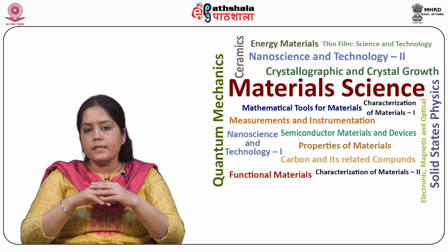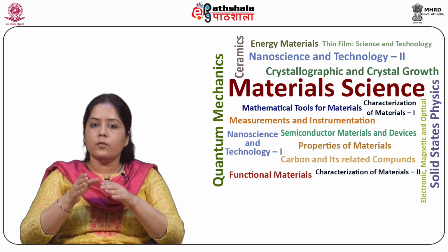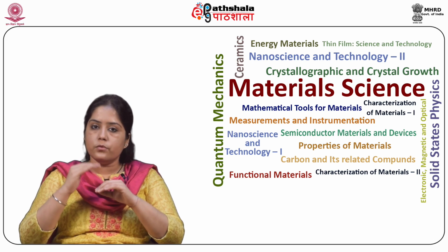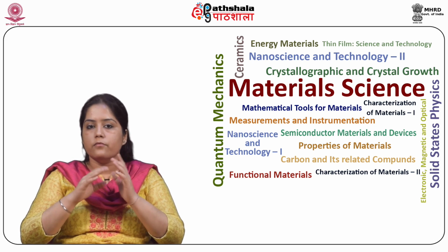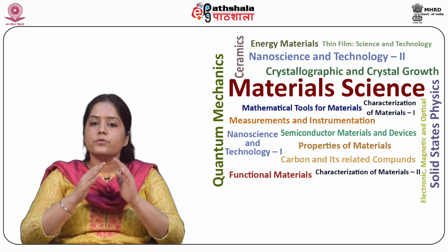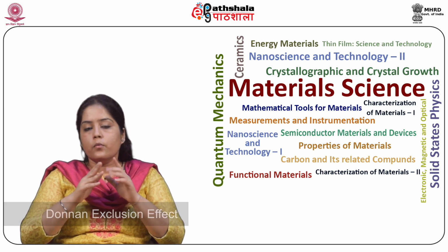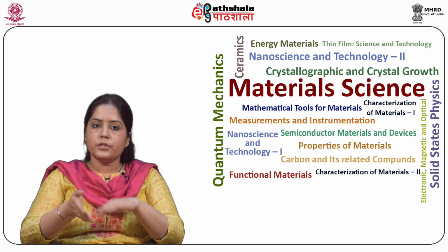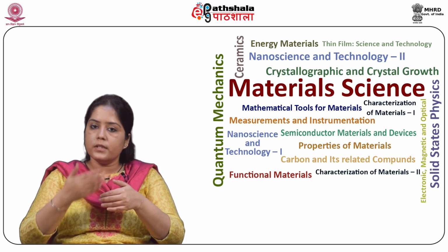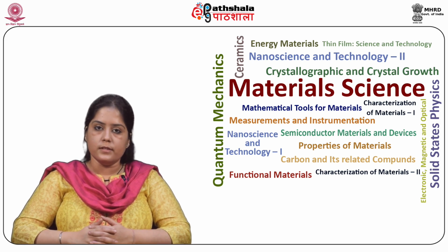However, recent studies suggested that AEM could effectively reduce the crossover of vanadium ions in VRFB due to the Donnan exclusion effect, which is an electrostatic repulsion between the cation groups within the membrane and the electroactive species.